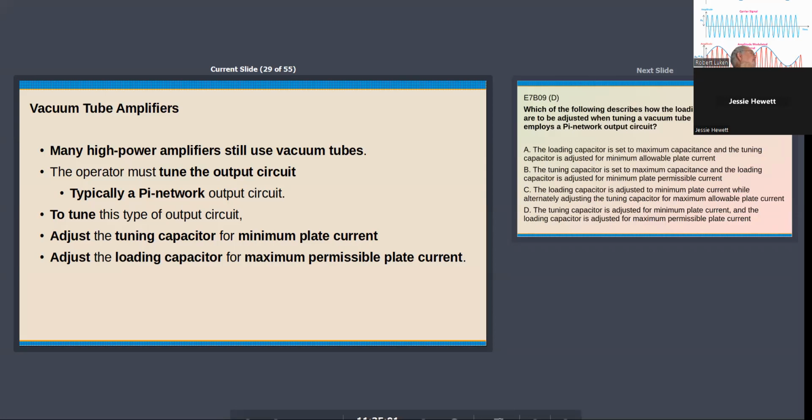There's no modulation of any kind on CW. FM shouldn't be affected. Constant amplitude, they're just changing frequency. Some of the digital modes, perhaps, which are also fixed amplitude. Phase modulation or PSK should work. Exactly. So it's not like class C amplifiers are never used, there is a place for it.